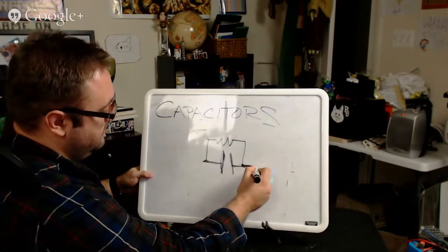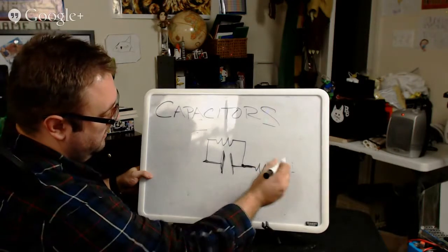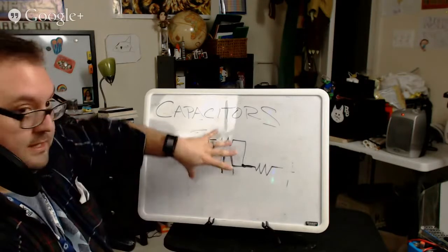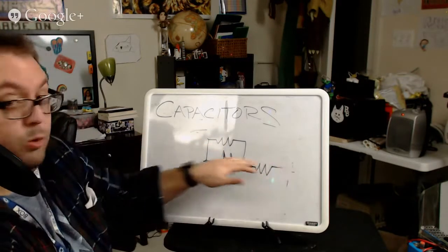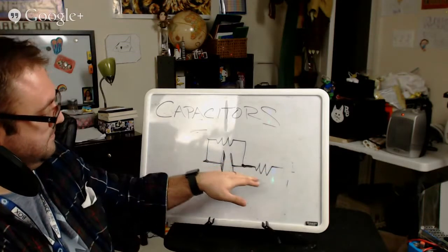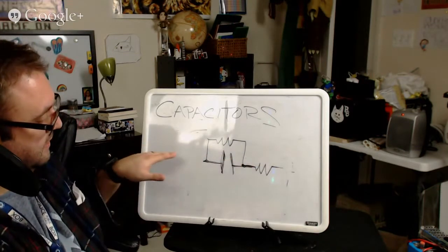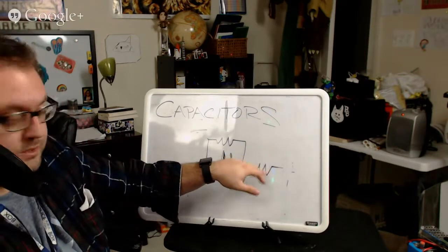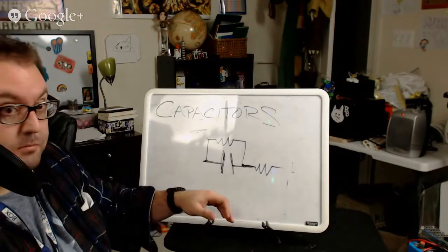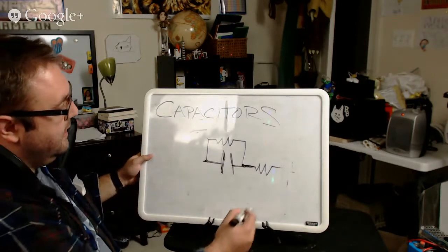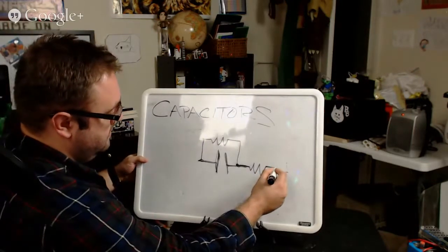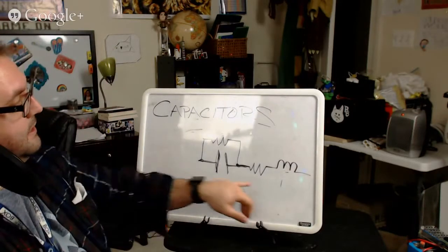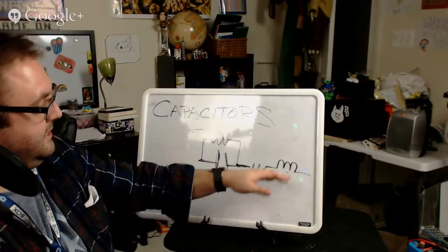There's also what's called the equivalent series resistance. Ideally there would be no loss in the capacitor, but some of the voltage does get burned up. There's a little voltage drop, so there is some resistance. And there is also, and we haven't talked about this part yet, it's coming up tonight, the inductance. There is equivalent series inductance as well.